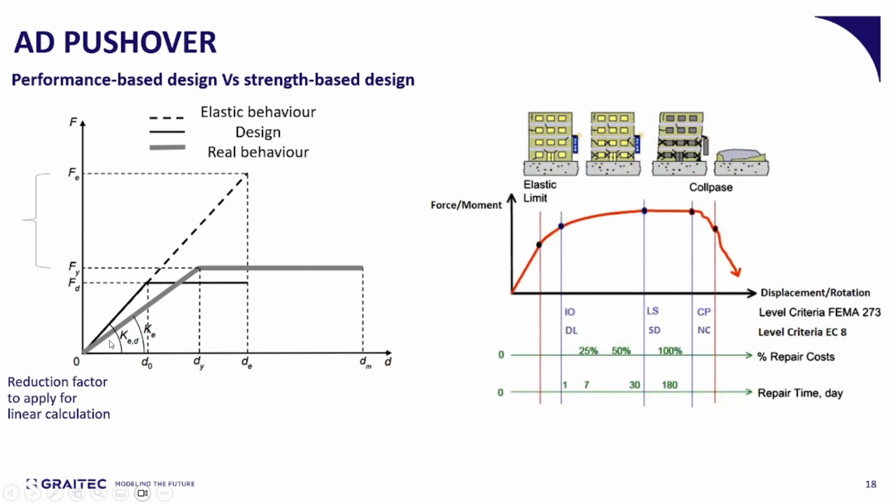Here is the real behavior. The real behavior is different from the elastic behavior because the structure will never perform elastically. And the reason for this is the material nonlinearity. The material will yield as the structure develops its internal forces. Therefore, we will never get this point.